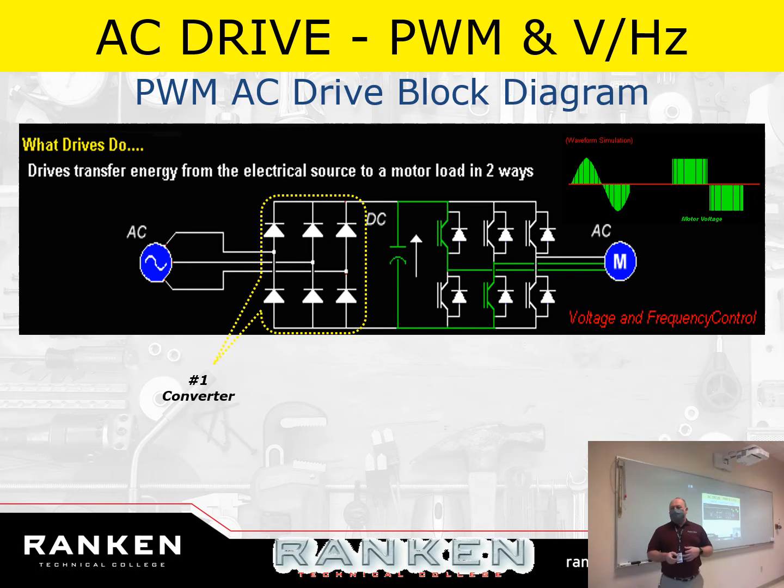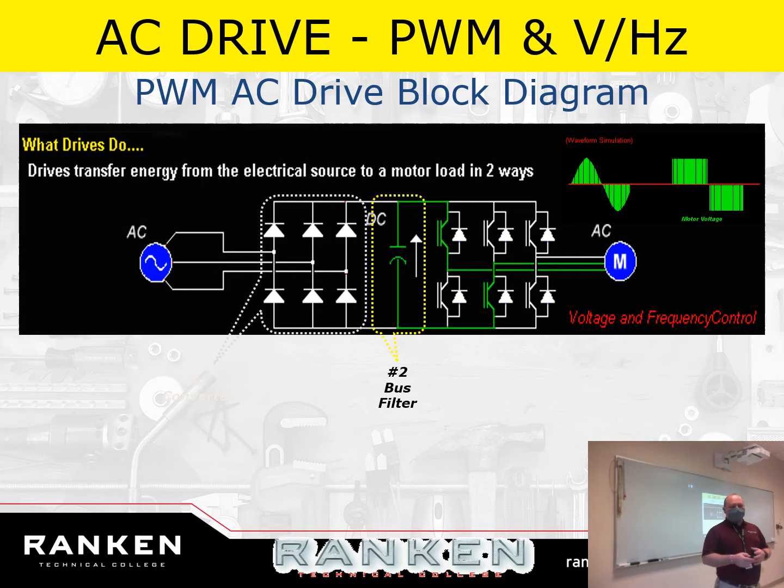That is correct. It's made up of a series of diodes, a bridge rectifier. The next part's called what? A capacitor or a filter, right? Sometimes you'll see a little inductor in series with the capacitor that is called a choke filter. Some of them have it, some of them don't. It just helps smooth it out a little bit better.